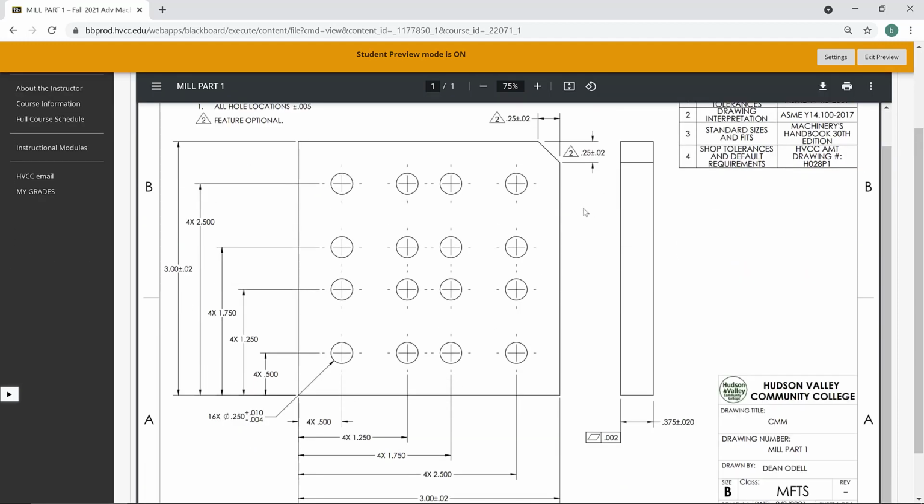And to keep it simple, we're going to program it just like this. Okay? There is a tooth out flatness. We are going to ignore that in this example. We're also going to ignore the 3/8. These parts should be 3/8, but I'm not going to worry about facing this part off. The only thing we're going to do is spot drill and drill all of these 1/4 inch holes. Okay, we're going to ignore this chamfer. This would be our first assignment. There are a couple examples in this.